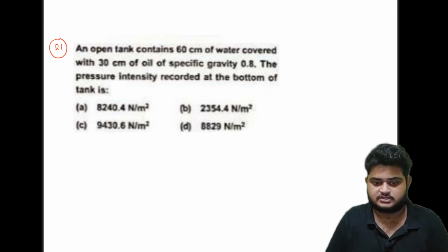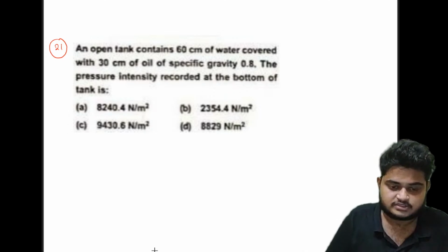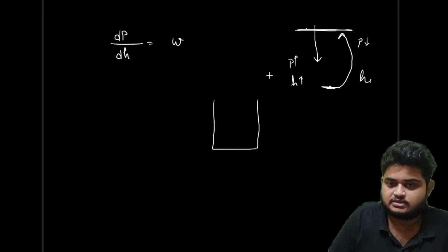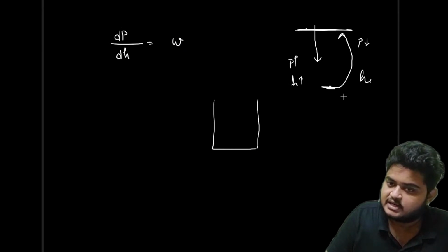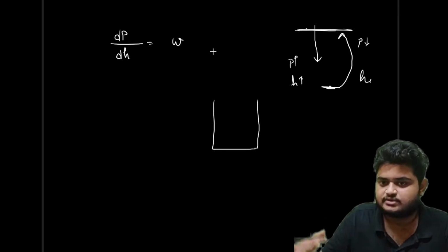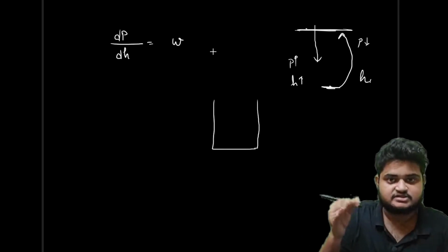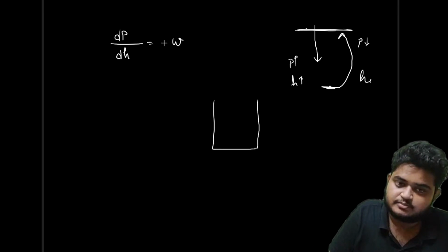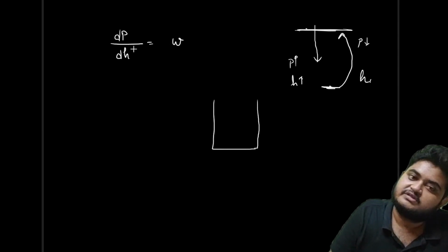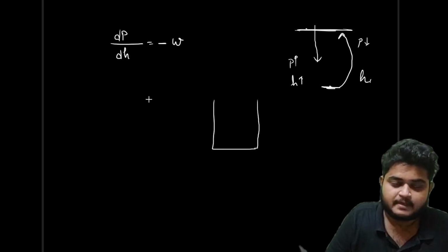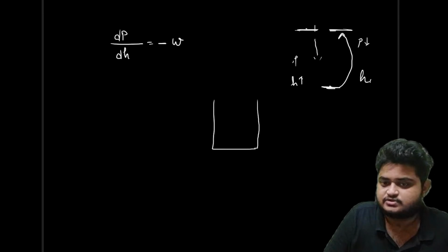So this is the hydrostatic law which I am going to use in the next question, but let me complete it: if the depth increases, the pressure increases with the depth, and if the height is increasing, the pressure is actually becoming less, right? So this will be the formula. If this is for height, it will be minus. Okay, now in this question it is not actually needed.